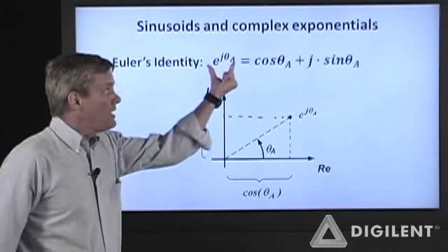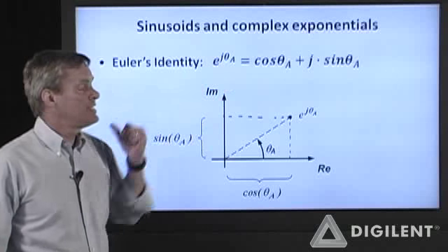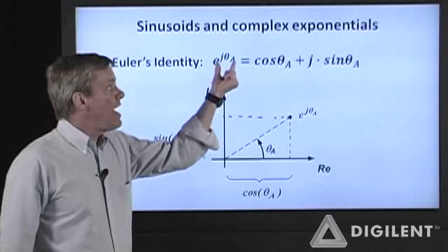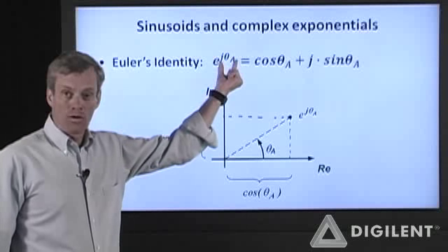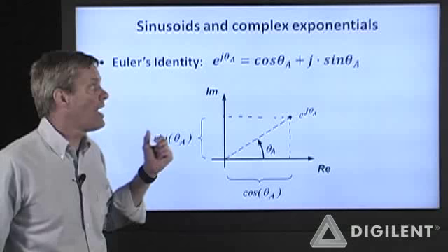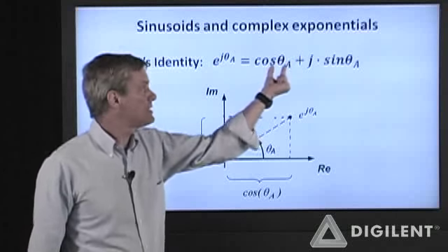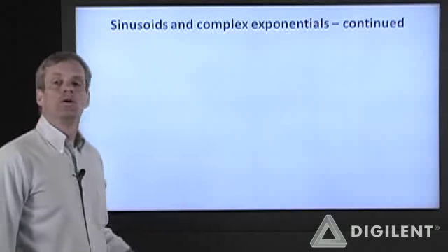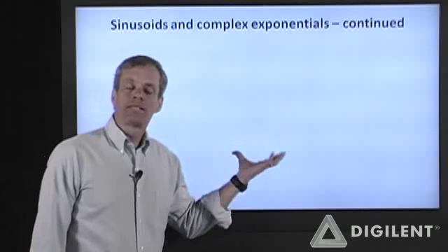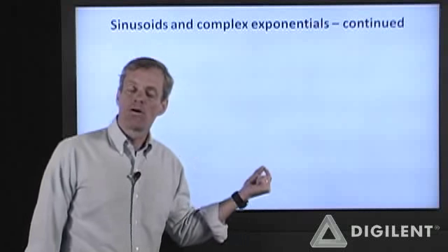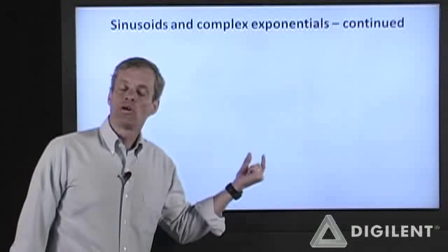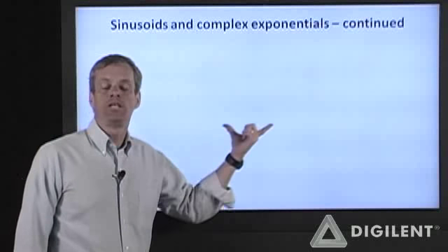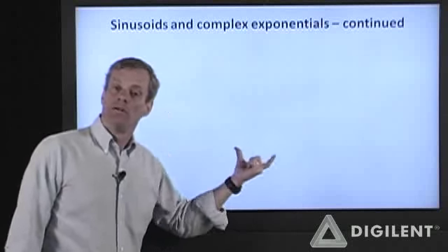So, complex exponentials are intrinsically tied up with cosines and sines. What we're going to do next is allow this coefficient here to vary with time so that we can get a cosine of omega t by making this a j omega t. So as I mentioned previously, we're now going to take this concept of a complex number being represented as a sine or a cosine, and generalize that to a function in the complex plane, which is generating a sinusoidal function with time.